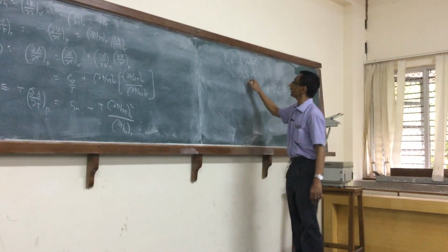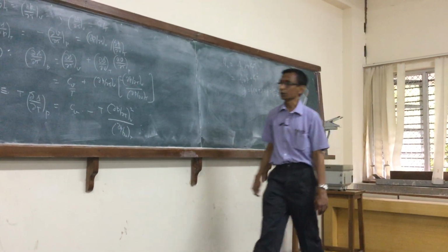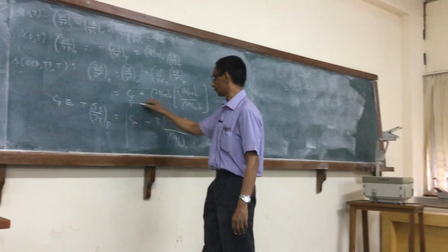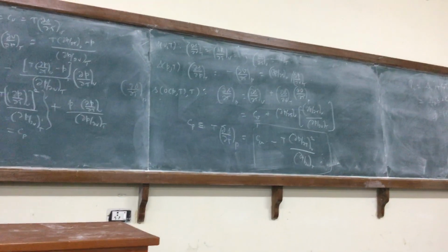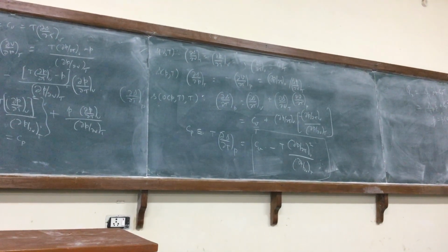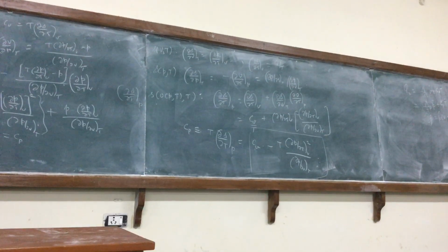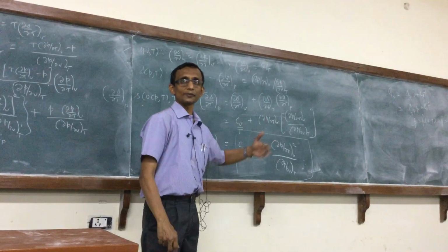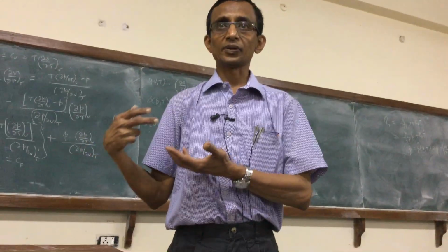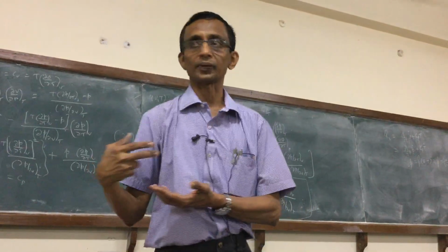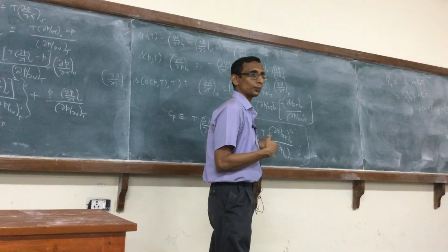If I substitute that here, I get a relationship between lambda V and lambda P, and Cv and Cp, and you will easily verify that Cp is related to Cv by this relation. So all the equations based on equilibrium are consistent with the relations of classical thermodynamics of reversible processes. Since we obtain Cp to be equal to this, I can now define Cp to be this.